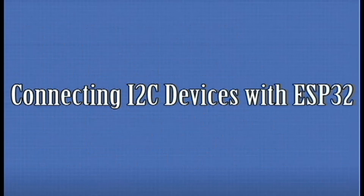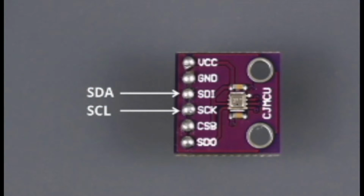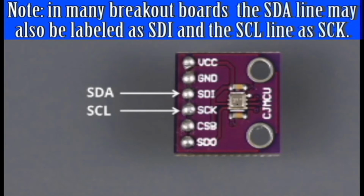Connecting I2C devices with ESP32. I2C communication protocol uses 2 wires to share information. One is used for the clock signal, SCL, and the other is used to send and receive data, SDA. Note, in many breakout boards, the SDA line may also be labeled as SDI and the SCL line as SCK.